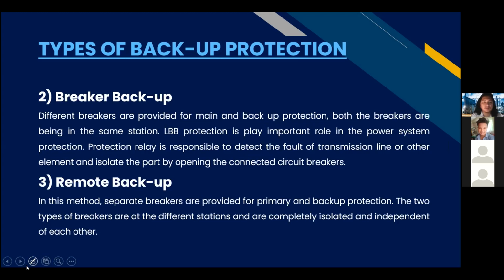The second type of backup protection is the breaker backup. Different breakers are provided for main and backup protection. Both breakers are in the same station. Breaker backup protection plays an important role in power system protection. The protection relay is responsible for detecting the fault of the transmission line or other element and isolating the part by opening the connected circuit breakers.